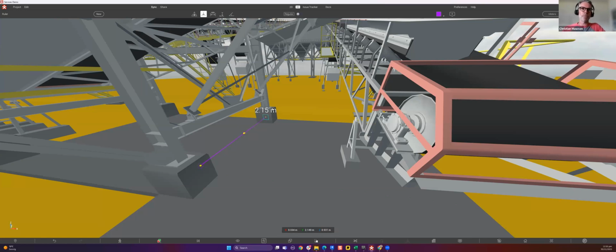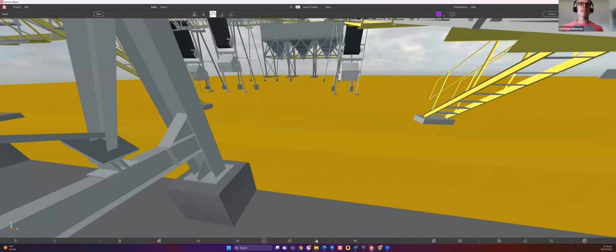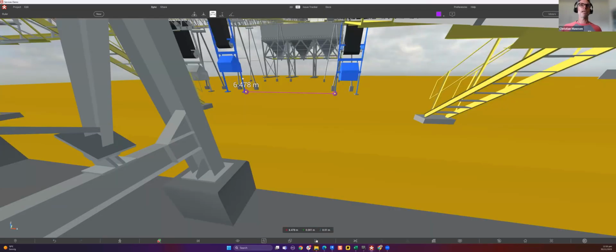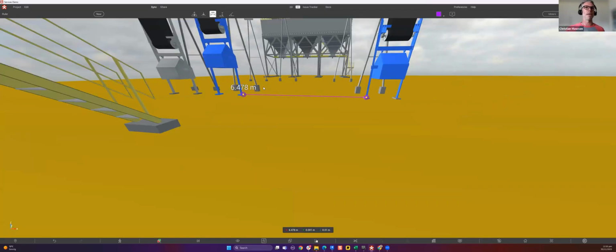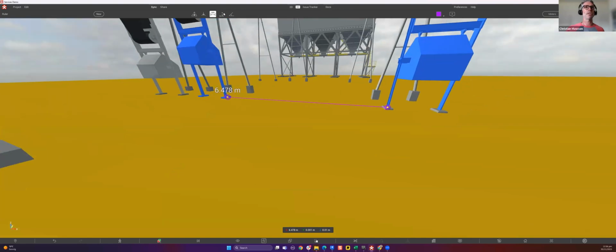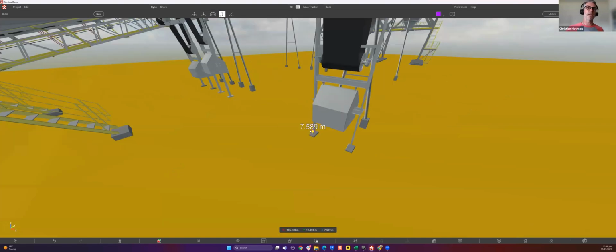into the issue tracker. So it's got all of the set out information on there. Various other ones, we've got point to point, so I can snap to points of these, get the diagonal, not super useful, but if I flick through my other dimensions, perpendicular, it's now giving me the height, or I've got parallel, which is giving me the horizontal distance. Minimum, I select a couple of objects like that, it will just give you the minimum dimension between those two objects really quickly.